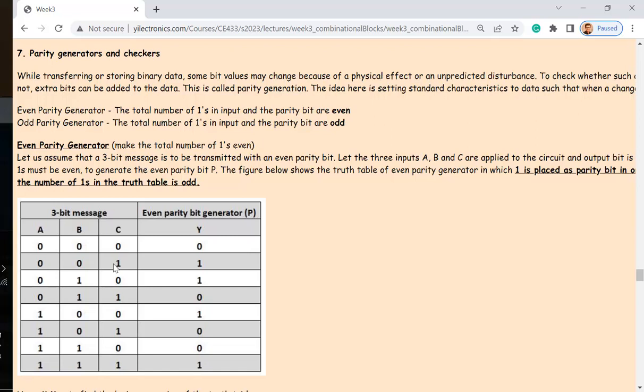There's nothing wrong with the data. The data is the data, okay? But there's just an odd number of ones. We need to make it up. We need to make it into an even number of ones. So the actual parity bit generator needs to detect that and then generate the 1, so you can send 4-bit data. It's always 4 bits, right? So you have the 4 bits of data, but the parity bit is going to be 1. Okay?